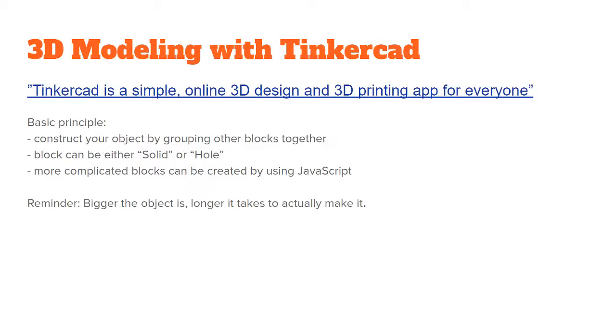That's the design process. Then you can translate that into the 3D printer, as long as you remember some things about 3D printing. So minus 45 degrees minimum angle. Okay.